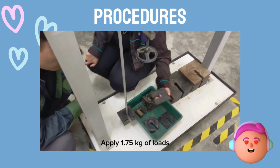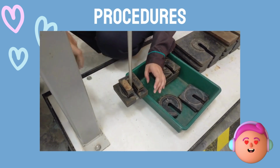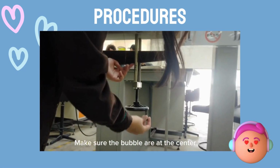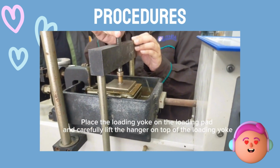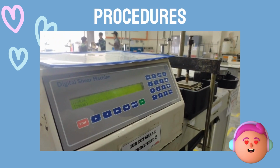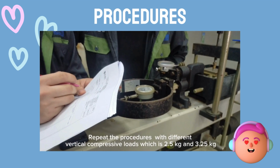Then, apply 1.75 kg of loads. Make sure the bubbles are at the center. Place the loading yoke on the loading pad and carefully lift the hanger. Lastly, record the horizontal and force gauge readings and repeat the procedures with different vertical compressive loads.